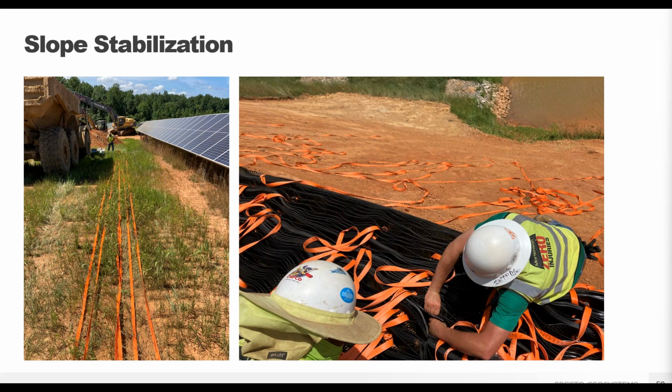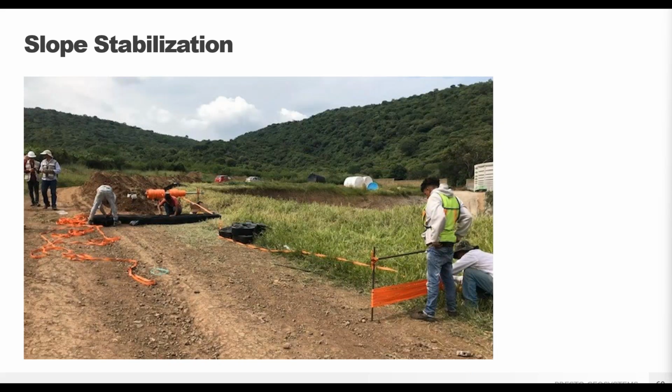Tendons were laid out, measured, and marked per design, then inserted through the eye slots on the slope crest, with sections being built on the flatter ground where it's safer and easier to work. A suspended rod through the tendon spools is a good technique tip that can be helpful when marking and inserting the tendons.